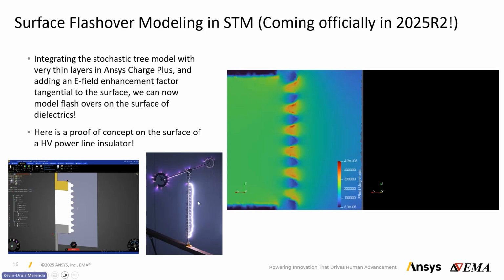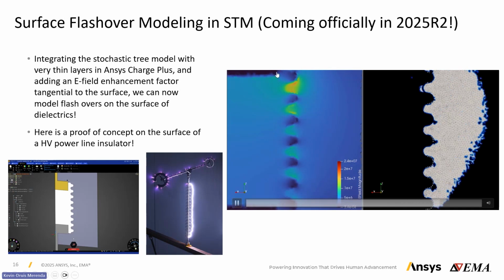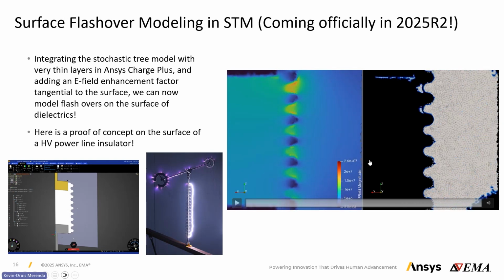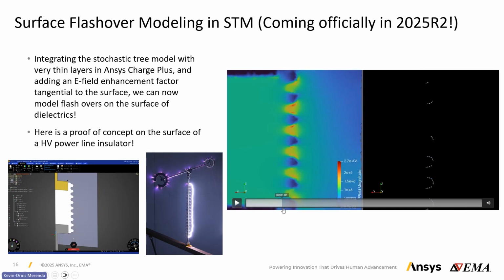And it's really zooming in on the early stages of what you see in the image in the center here, where you have a full-on arc established. So just to understand how that gets generated and what the breakdown voltage is for this is the tool to do it. In this image, you also see some other effects like corona discharges and things like that. And we have tools to also assess that based on the geometry and the problem of interest. So you can see here we ramp up the potentials in the fields, and then the dielectric will actually change over time at much longer time scale. And then what we saw was some surface enhancement effects where we have the discharge and the creepage happening along the surface of the dielectric.